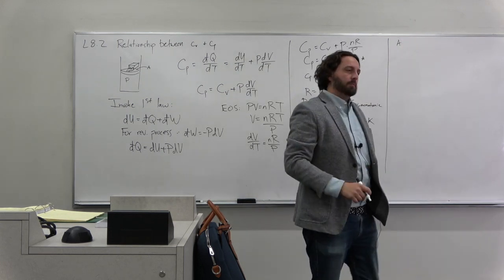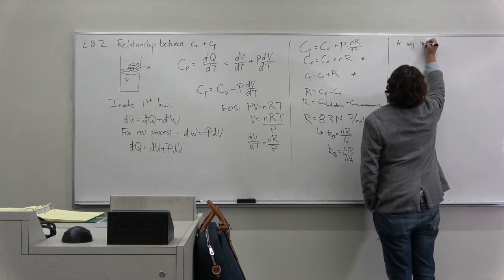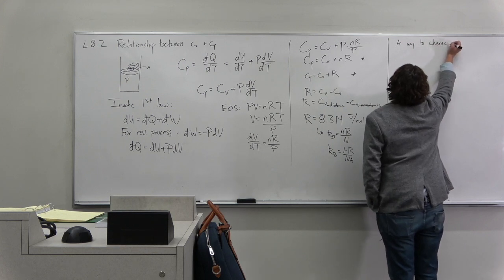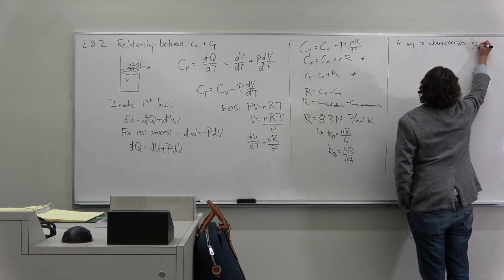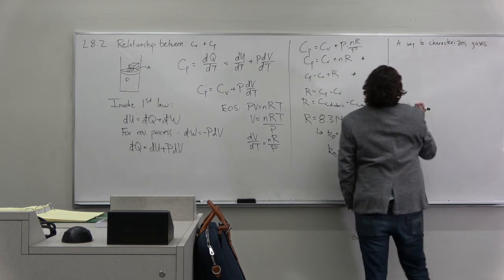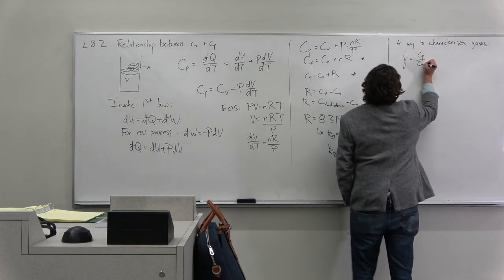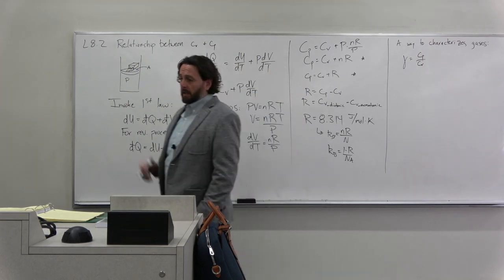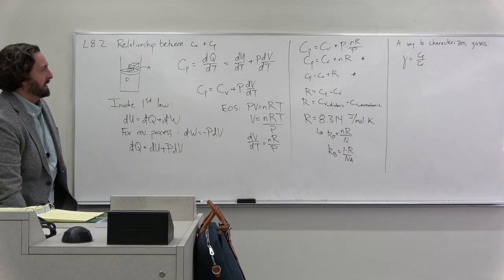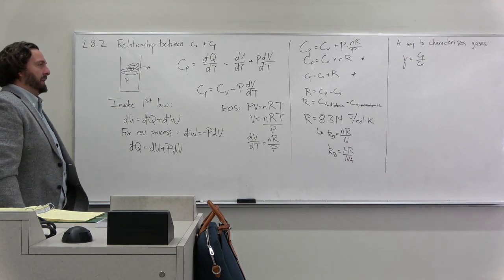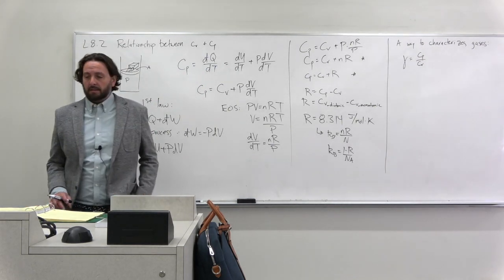So one thing that we're going to use to characterize gases is the ratio we're going to call gamma. So gamma is going to be Cp over Cv. So now you can see basically this is an intrinsic thing, so it doesn't even matter if it's big Cp, little Cp, per mass, as long as you're consistent.